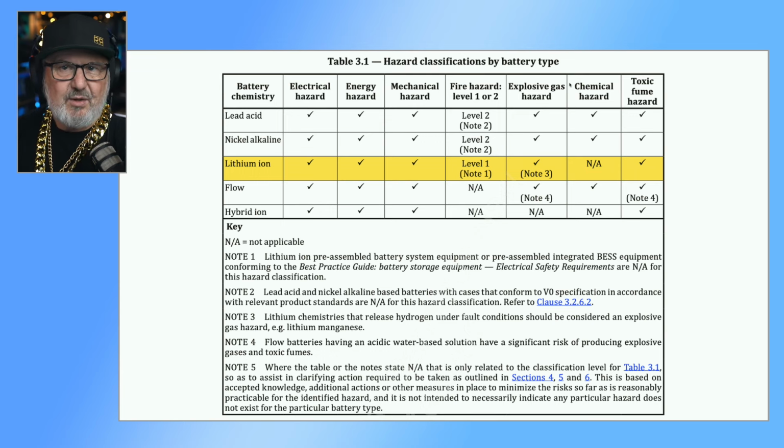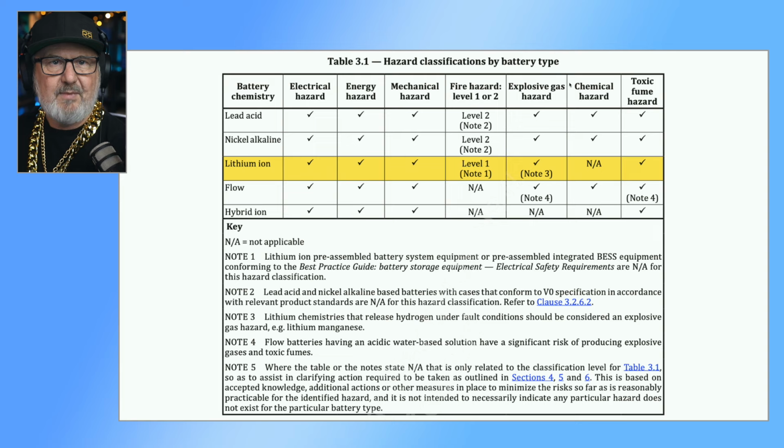Now, we've got a note 3 here. It's got a tick, which means it's mandatory, but then you read the note 3 and it says lithium chemistries that release hydrogen under fault conditions should be considered an explosive gas hazard. Fair enough. E.g., lithium manganese.